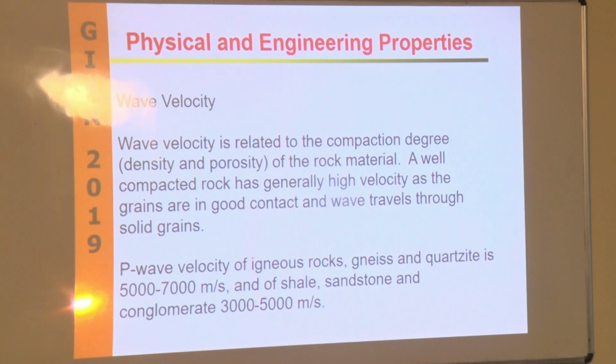So you can start counting. And even better, you can measure those in the three axes or several axes, and you have a feeling of how homogeneous that material is. Okay? And this is really important for a material like shales or gneiss, where you have some sort of bedding, sorry, foliation for gneiss.